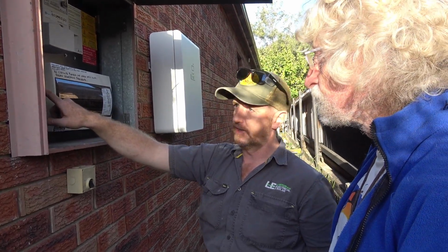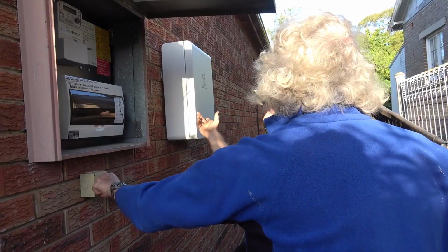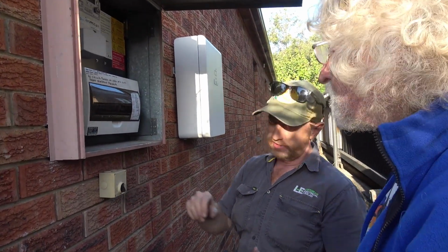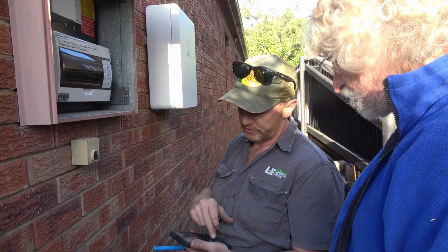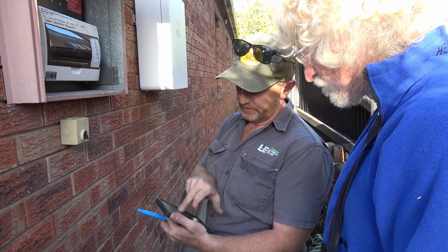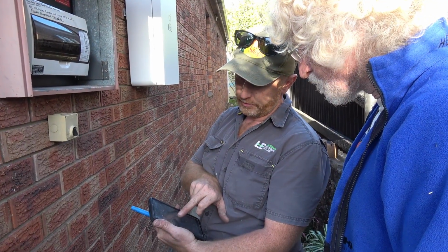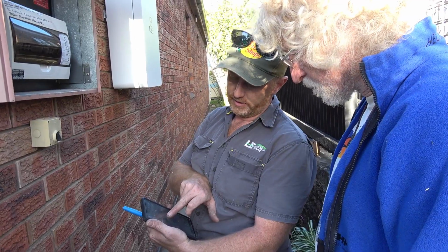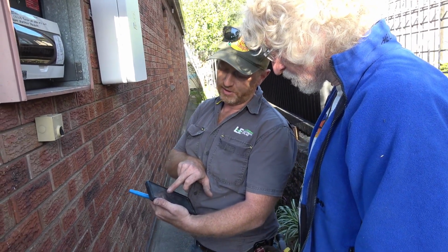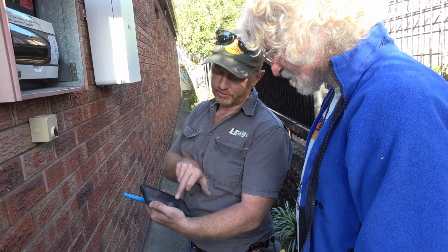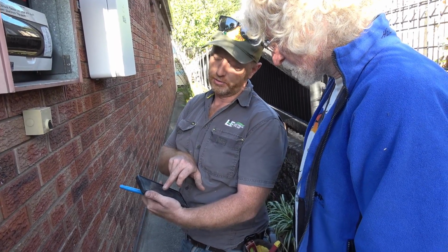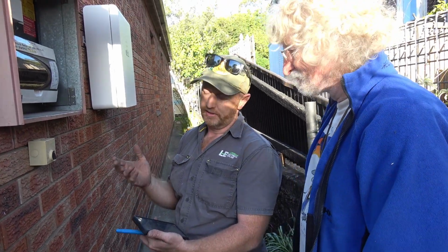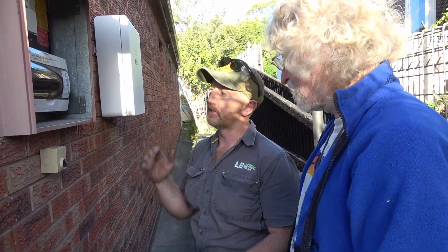So let's just say I was going to turn off the power. You hear a click here, power stays on, and you'll see that on the app. If there is an outage for whatever reason, you'll go into off-grid mode, and it'll tell you you've got 40% left in your battery. It won't give you an estimate on the time yet because your solar is still producing. But if your solar was dead, it would say you've got 10 hours left based on your usage at the moment. And let's just say the grid was down for a couple of days for some reason.